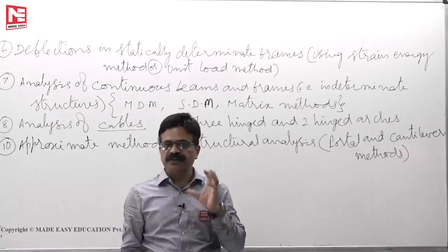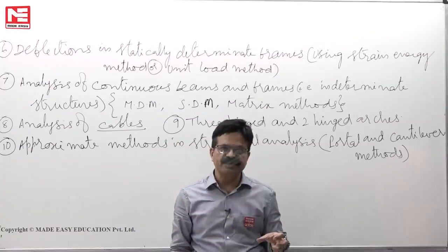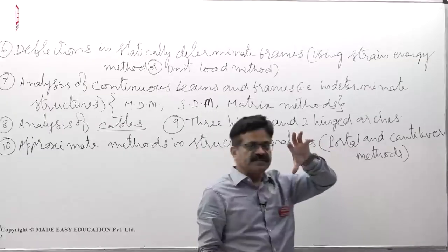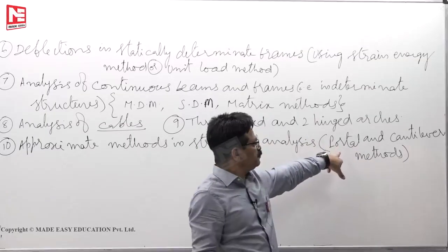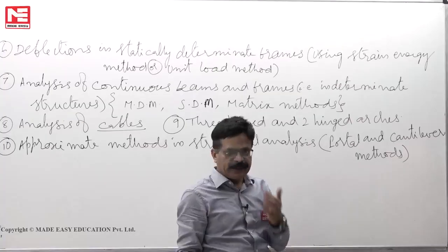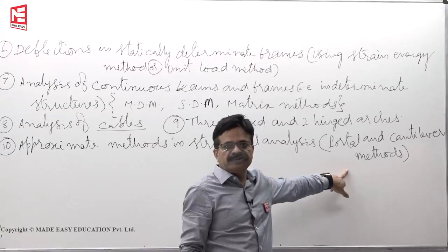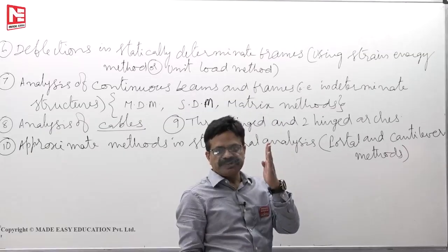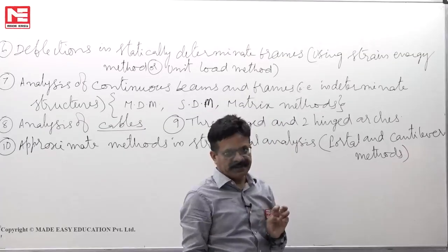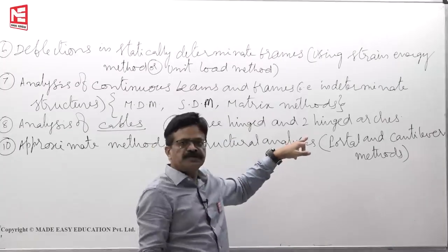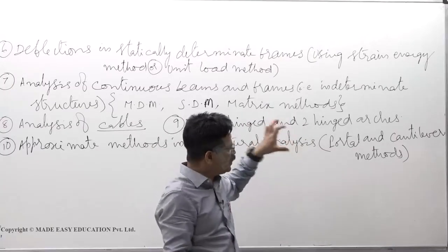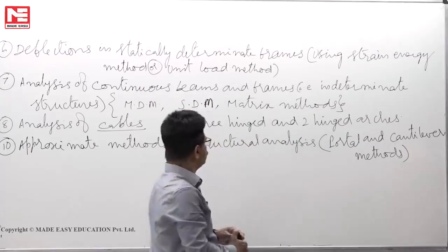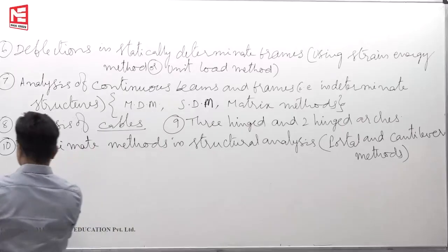steel structures, I have given you one concept about the design of battens, that is a frame analysis. IS 800 2007 has taken the portal method of analysis and derived the expression for the longitudinal shear force in the batten and bending moment in the batten. So, that is why we have to know about the portal method, because the understanding of this we use again in the design of steel structures. Okay. Next, we have